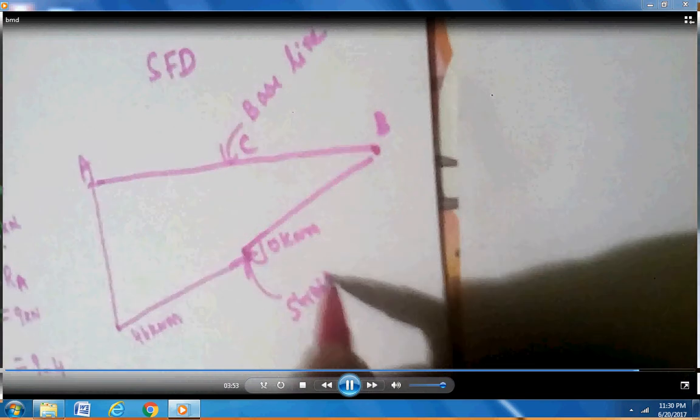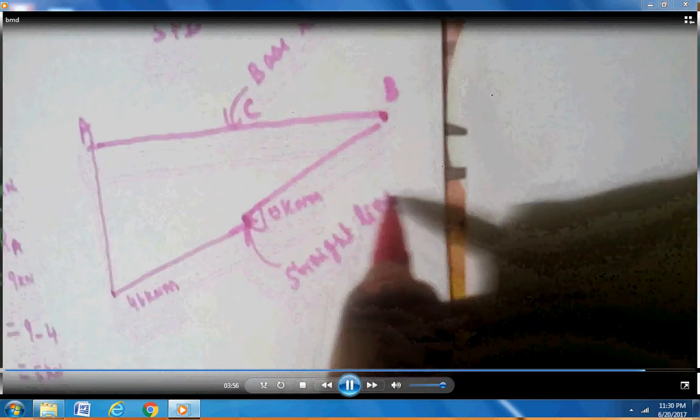Here Mh, the bending moment at h, is minus 5h, so it satisfies the condition of a straight line. So connect the points as straight line, first B to C, then C to A. In this bending moment diagram all of the sign is negative, so put negative sign.